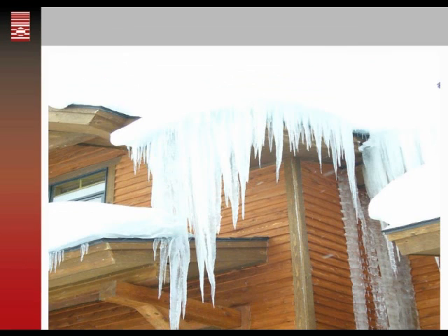Those of us in cold climates, that have the luxury of living in cold climates, we can see when we have problems with pressure boundaries and thermal boundaries not lining up properly, because we start seeing huge ice dams, long icicles, and water backing up into houses behind these ice dams.